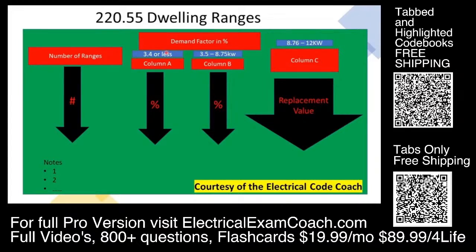Starting on the left-hand side in column A, this is when your individual range falls at 3.4 or less kW. Column B is when the individual range itself falls between 3.5 and 8.75. Then column C is when our ranges are 8.76 through 12 kW. Then in the bottom left-hand corner of the table, you're going to see some notes. Those cover situations that don't fit into the normal table, and we're going to take it piece by piece. Let's get to it.